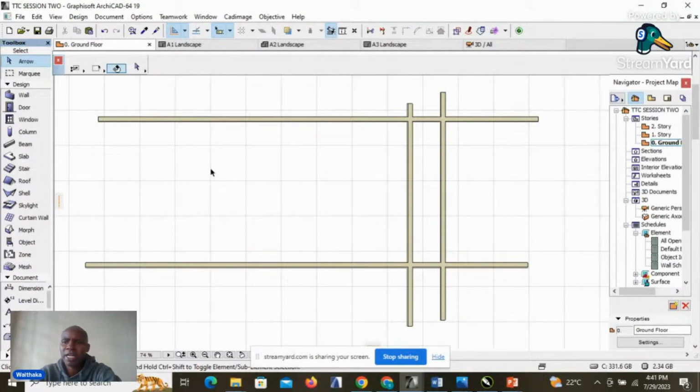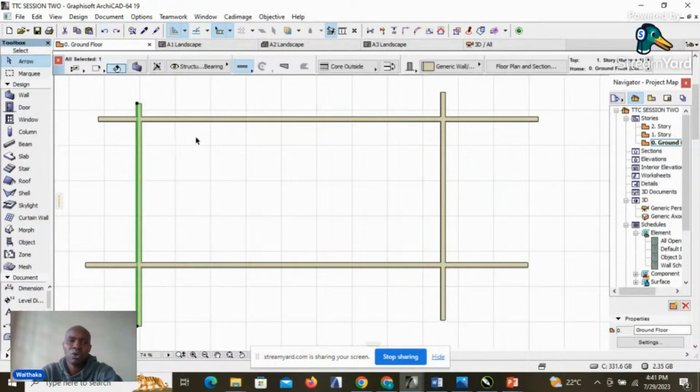And the command drag, as I said earlier, does not leave a copy. So now we want to see how we can drag a copy. We can drag a copy of this wall. Again, if you want to go back, you can use the undo and the redo command. Undo and redo will always take you a step back or a step forward. So we want now to look at the drag a copy command and see how we do that.